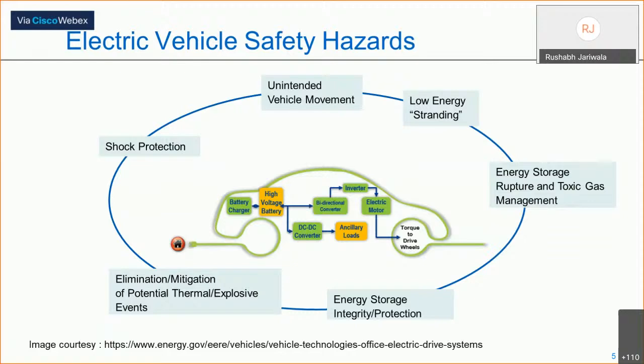So that's another new kind of hazard, which is not there with gasoline vehicles, where those things were not that toxic. And another thing is that either petrol or diesel has its own smell that gives an immediate indication to the passengers that something is wrong. But with the Li-ion battery, the gases are odorless, and that creates another inherent issue.